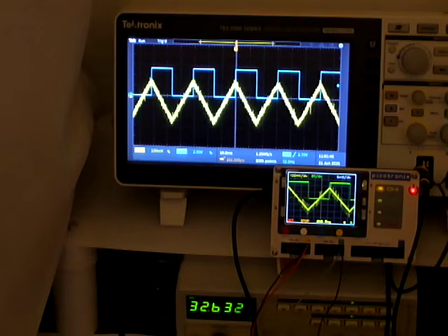So an interesting thing here is that on that range of 100 millivolts per division, we're actually doing some tricks. We take the 12-bit of the ADC and we're moving it up to 16 bits, and then we're doing an averaging and also finding the min-max, and when it's drawn, the noise, if you like, is drawn as a sort of lighter background color, which is like phosphor. And if you see, the main triangle trace has been filtered and averaged, so it's looking quite solid. So we're seeing a solid triangle.